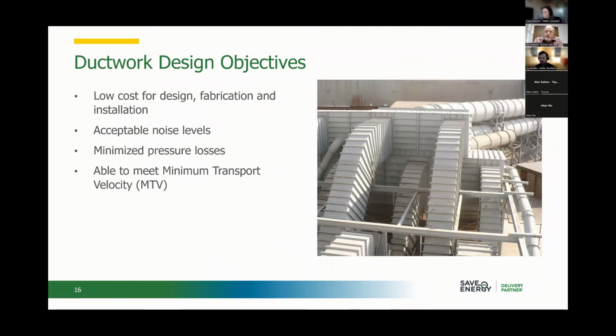In the commercial world, if I recall correctly from my years of testing HVAC systems, you might have velocity as low as 1,000 feet per minute, more likely around 1,500. And I think by the time you hit 2,000, you've got a pretty good flow coming through your ductwork. Well, the reason why this becomes important is because your pressure losses increase as the square of the velocity, and therefore the square of the flow value that you're trying to push through your ductwork.